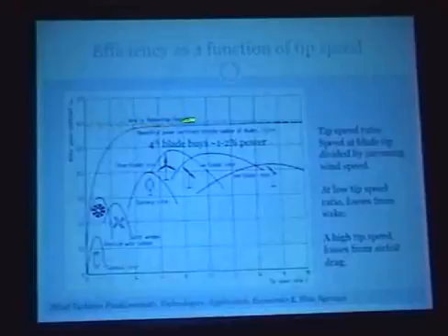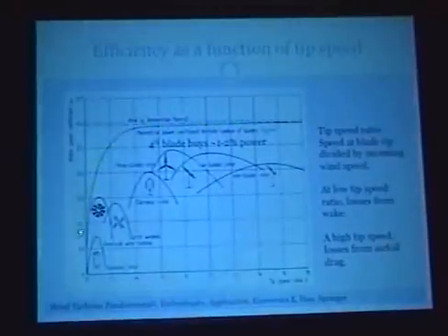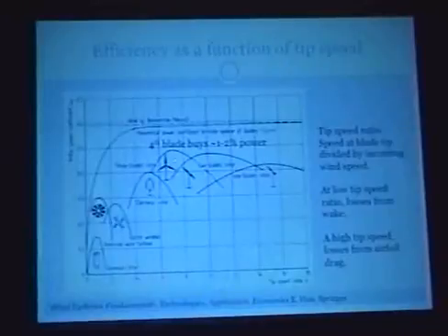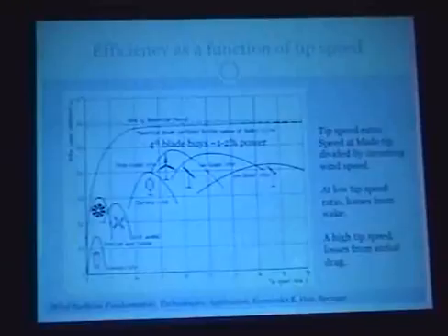So at the top here is the Betz limit, and this is just sort of a momentum theory. Now, if you include the spinning wake, you find that, I should say that the x-axis here is the tip speed ratio. So this is how fast the tip of this blade is moving relative to the incoming wind speed. So say right here, if the tip speed ratio is 10, that means if you have a 10 mile per hour wind blowing at your turbine, the tip of this blade will be spinning at 100 miles per hour. So this is really moving quite a bit faster than the wind.